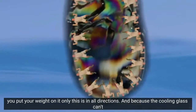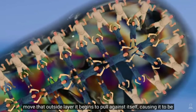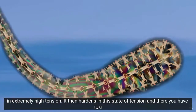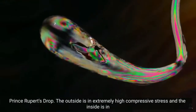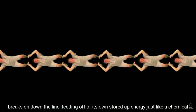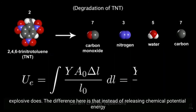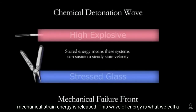Now, because the cooling glass can't move that outside layer, it begins to pull against itself, causing it to be in extremely high tension. It then hardens in this state of tension, and there you have it, a Prince Rupert's drop. The outside is an extremely high compressive stress, and the inside is an extremely high tensile stress. If one link in this tension chain is ever cut, it breaks on down the line, feeding off of its own stored up energy, just like a chemical explosive does. The difference here is that instead of releasing chemical potential energy, mechanical strain energy is released. This wave of energy is what we call a failure front.